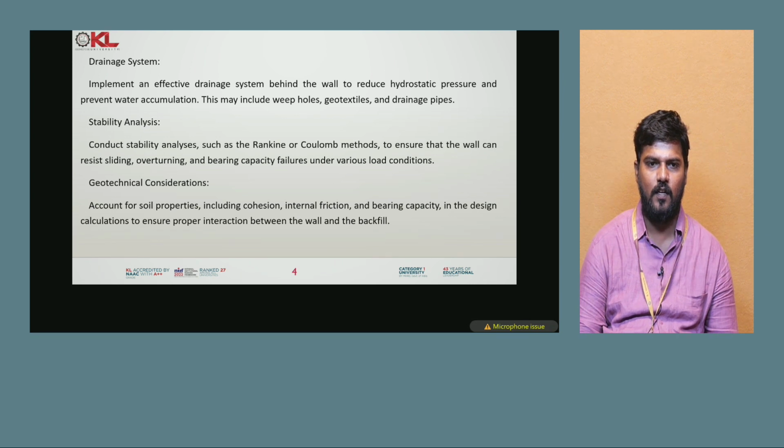Next one is the geotechnical considerations. Account for soil properties including cohesion, internal friction, and bearing capacity in the design calculations to ensure proper interaction between the wall and the backfill.